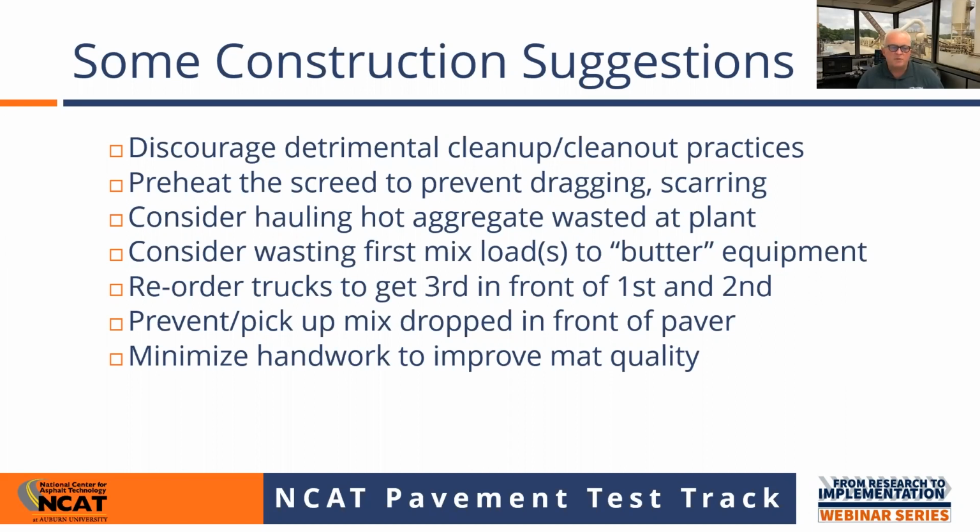Many times on our paving crews, we think, hey, we've got the crew out there, people need to be doing something, so we just instinctively jump in and do a lot of hand work. But especially with OGFC, especially when you're pulling off that transverse joint, when you're starting that run, it's better to not do any if you can help it.